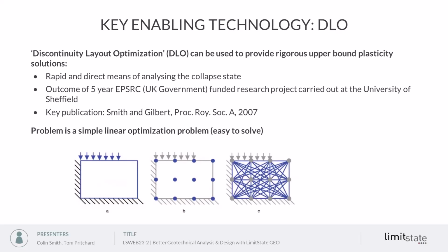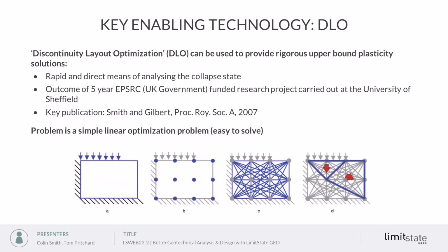And then we use optimization to pick out of that set of slip lines. In this case, we've got 12 times 11 over 2, 66 possible slip lines. Out of that, we can use optimization to find those slip lines that give us the critical failure mechanism, or the one that dissipates the least energy at collapse. So that selects out 6 of those slip lines to give us this particular mechanism.